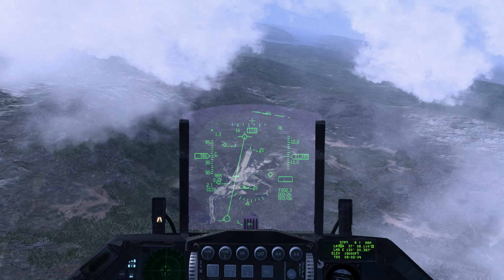With all bombs released, we will begin the Climbing Safe Escape Maneuver, or CSEM. We will set full military power and pull to 20 degrees of nose up in 2 seconds at 5 Gs. You may count out the timing with 1000, 2000. You may then continue to pull to 30 degrees at a lower rate. The purpose of the maneuver is to avoid the frag envelope as the low drag bombs, falling ballistically, hit the target, but be careful not to overstress the aircraft.